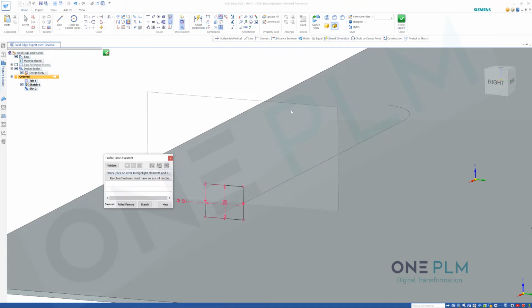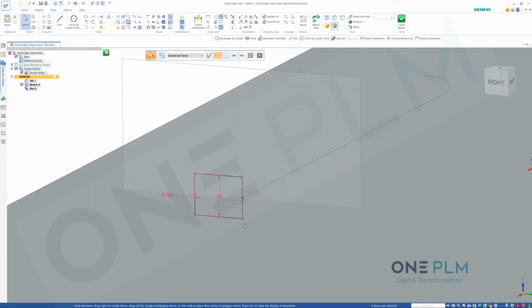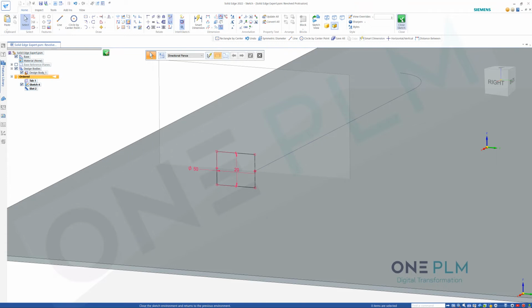And then when we close that sketch, if we haven't done our axis of revolution, make sure we do that. If this option comes up, validate allows you to revalidate. It's just done that, so we don't need that. Delete feature will get rid of it. Sketch will turn this into a sketch. So for this, I'm just going to do a red cross, and I'm going to go onto here and say axis of revolution is this line, and it's going to turn it into my axis of revolution line.